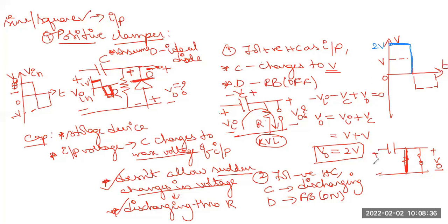So finally, what is the capacitor voltage here equal to? Now if it is a negative half cycle, you have minus plus, right? That is minus plus. Now the polarities here, for the negative half cycle: this is minus, this is plus here, because I'm talking about the negative half cycle. Now this is shorted, because of which the capacitor and resistance also become shorted.